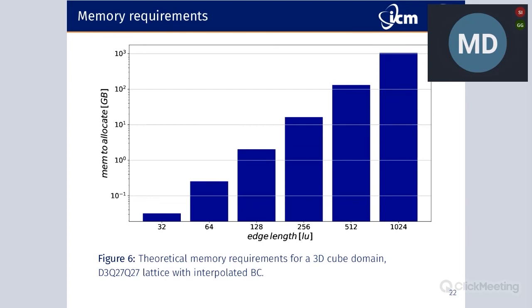So a single cube in 3 dimensions with 1,000 nodes in each direction is not very big, but it is almost a terabyte of memory. If you would like to simulate cars or planes, that would be 2 or 3 orders of magnitude bigger. So Lattice Boltzmann is rather confined to phenomena that could fit in 1,000 cells, maybe 2,000.